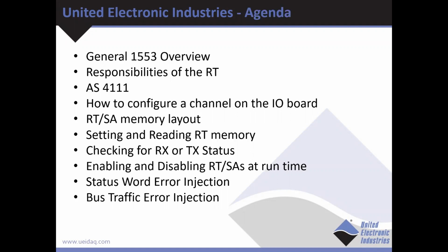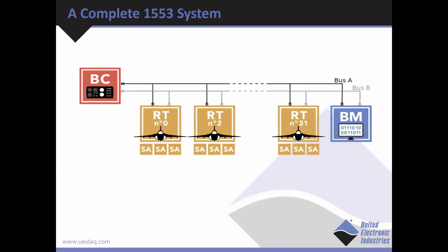We'll be talking about RTSA memory, setting it and reading data from it, also checking to see if something was received or transmitted, as well as enabling and disabling RTSAs at runtime. And lastly, error injection. A typical 1553 system will have a bus controller, up to 32 RTs, and each RT will have 32 subaddresses. And there's an optional bus monitor that allows you to see what's going on the bus.